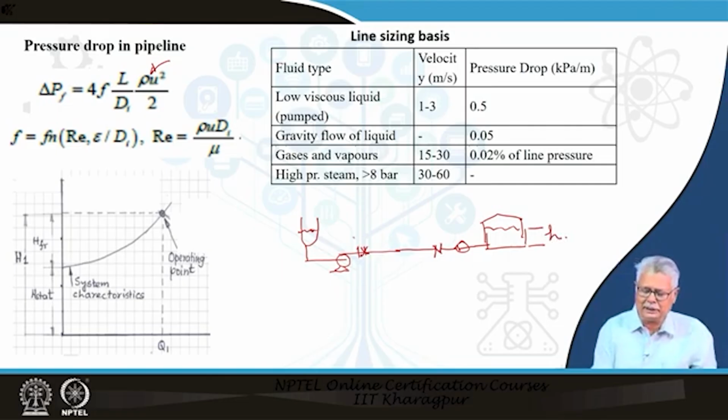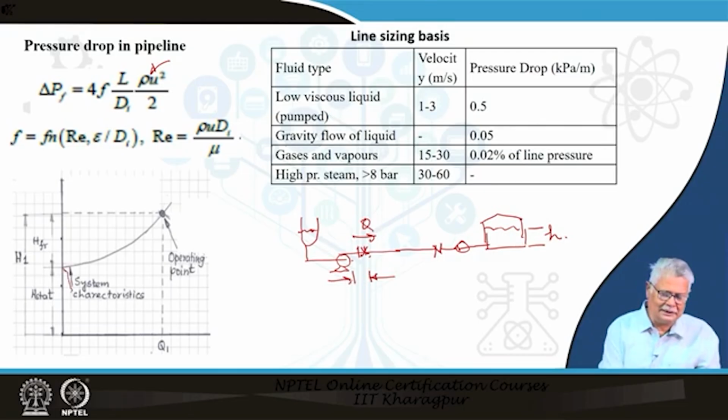So even when my flow rate through this is Q, there is a differential pressure across this. This basically is the initial differential pressure, and the corresponding head is this. It is due to the static head difference between these two. Now, the moment the flow starts, there will be frictional losses which can be estimated by this equation, and you know the procedure already.